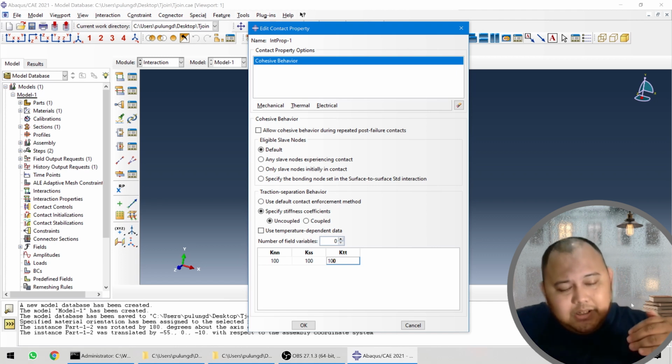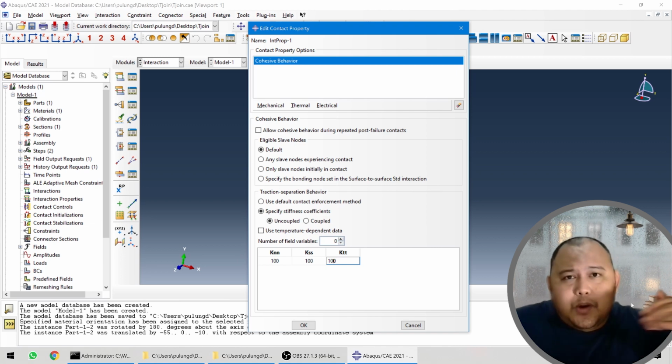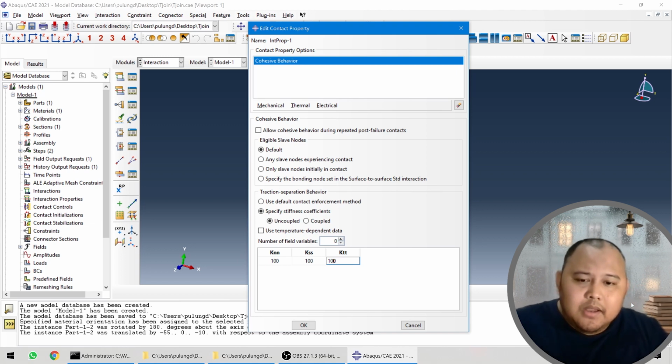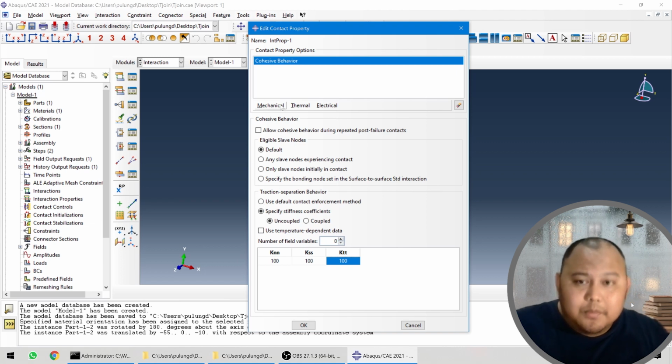So what you need to do is basically to use a low value like 1, try 10, try 100, check where's the maximum you can get, but at the same time maintaining that your simulation can still converge, right? So here I tried, if I use 100 it will still work, 200 works, 300 works, 400 works, 500 it fails. So the maximum value I can use is around 400 to 500 maybe. Okay, so in this simulation I will use 100, but you can even try what I just said, try to use the default. Maybe it can converge, I don't know, but I tried before.